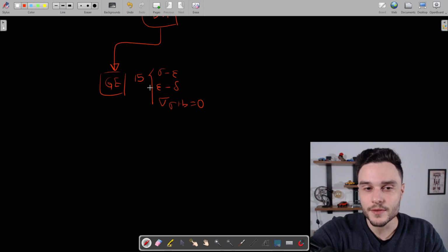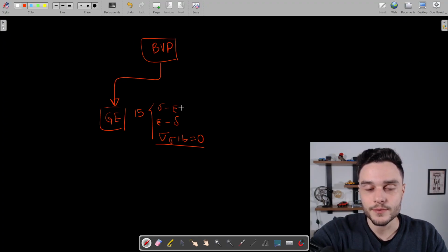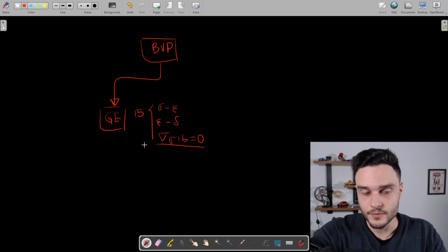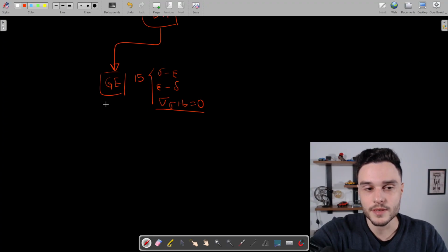We have defined these already because we have defined the kind of element formulation, which is S4 and S3, and we also have selected the static solver. So when we do this, we have defined all this information, right? And then here we have the assumptions considered. So we have activated the large displacement nonlinearity, right? So we are going to allow large displacements.